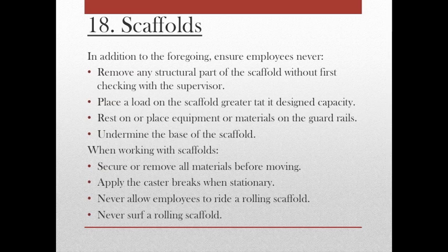When working with rolling scaffolds, secure or remove all material and equipment from the platform before moving the scaffold. Apply the caster brakes at all times when the scaffold is stationary. Have sufficient help available when moving the rolling scaffold. Be alert for hazards such as holes or openings in the floor, overhead obstructions, slopes, and debris. Never allow employees to ride on a rolling scaffold.